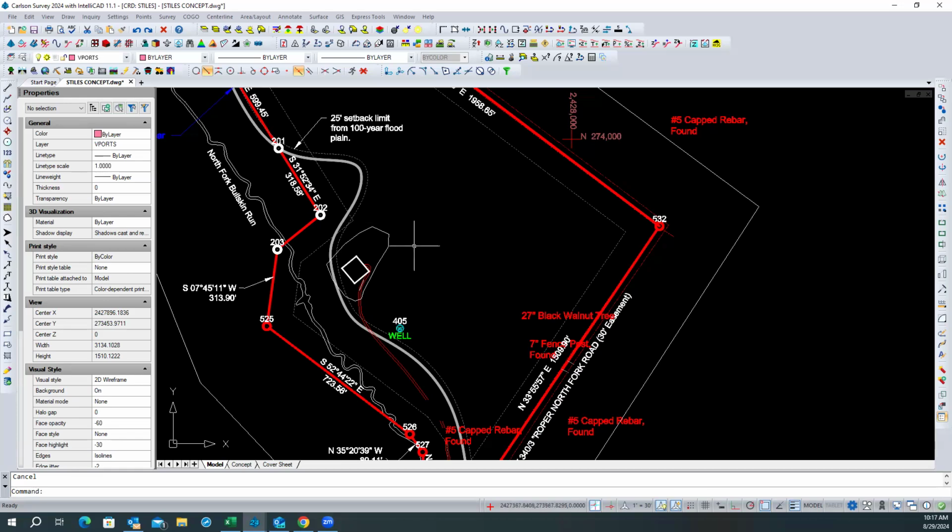But at this point, now that you've changed this to say 1 inch equals 30, and you see that down here on my annotative scale, when you go to type a piece of text or annotate something and it asks for the text size, when you say 0.1, it knows you mean 0.1 inches and it takes care of multiplying all that out. And even if you're not using annotative text, it will set it for the correct size as to whatever your scaling is set to right now at the time you do it.